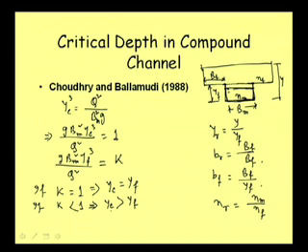Well, now what does it indicate, yc greater than yf? It means critical depth, if you just refer to this diagram, will be greater than yf, that means greater than this particular depth. So, when critical depth is greater than this particular depth, we cannot have critical depth below this main channel and below the flat plane level, and in that case that will not be valid, because up to this portion only we can have rectangular. So, we can consider this as a rectangular channel.